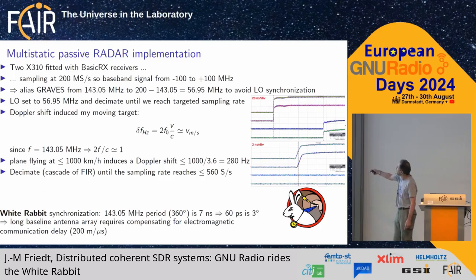when the first time I ran this, these are the 1 pulse per second from the CERN White Rabbit switches. These are 1 pulse per second from the GSI board. They're aligned to better than 1 nanosecond, so they're doing the job the way they want. However, you see that this is one hardware, this is another hardware, and there is a time offset between the two. So I just warn you, be careful when you're using the same gateware on an FPGA running on different hardware,